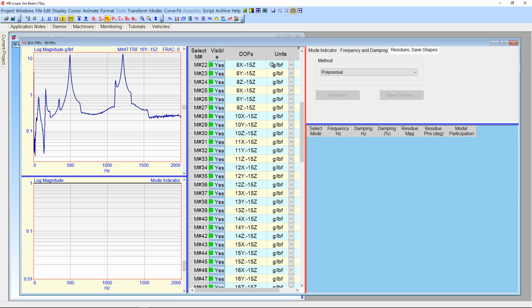For instance, in an operating or running machine, we're going to have peaks due to the RPM of the machine and multiples of the RPM. Those are called orders. They're going to force the machine to behave at those frequencies as a force response, and a resonance may or may not be involved. So with a running machine, we can measure a cross spectrum. That's called an output-only measurement. And we just have to assume that we don't know anything about the force, but it's a flat excitation.